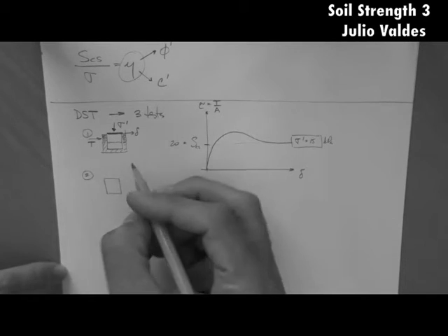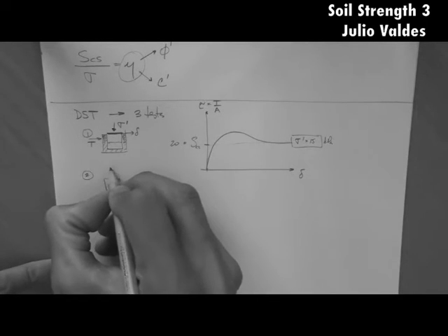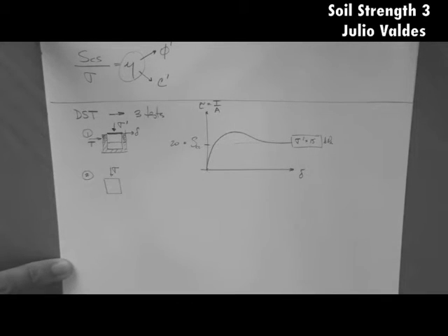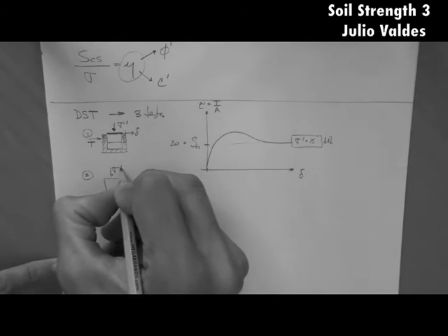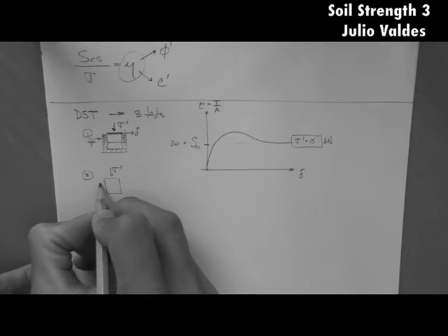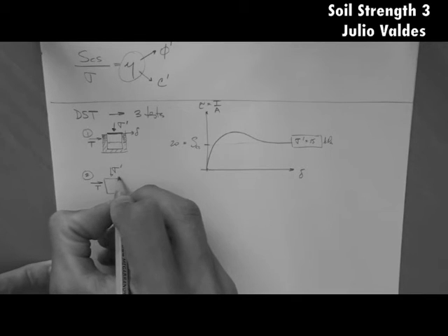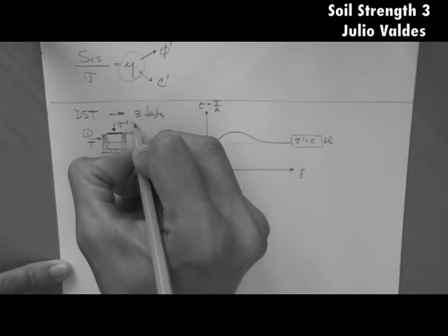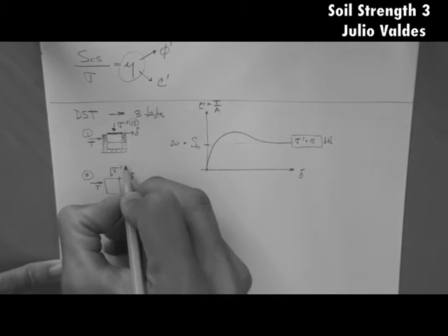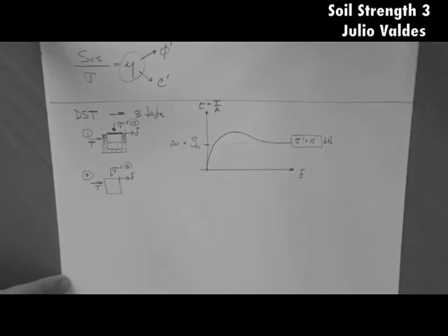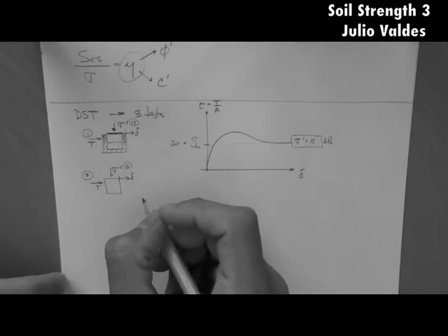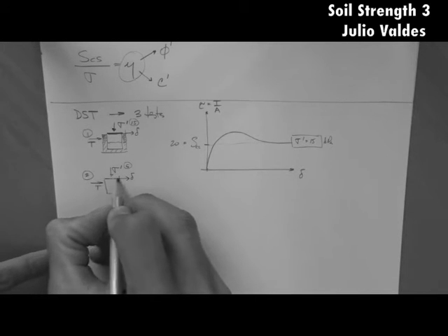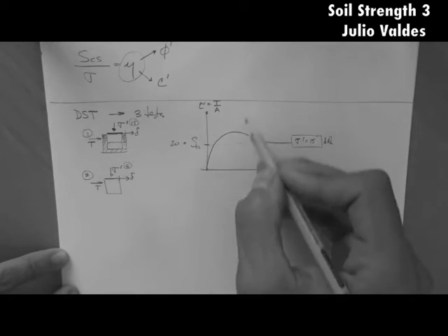Okay? So, same thing, you apply a stress, you wait for consolidation to end, therefore you can place a prime here. You run a direct shear test, and let's say in this was 15, right? Let's say in this case this is 5, so a lower stress. You impose a lower stress, you run the test, and you plot it in the same plot.